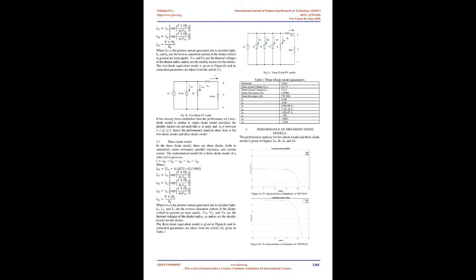In general, a PV module is modeled based on different series and parallel combinations of solar cells concerning the power requirement. With a series connection, the voltage profile of the module is improved, and with parallel, the current profile. The output from the PV module is dependent on operating temperature, irradiance, angle of irradiance, and resistance, series and parallel.